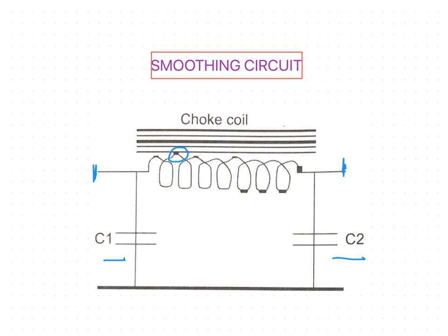When the EMF of the rectified current rises, current flows in the external circuit, and at the same time the condensers are charged. When the EMF falls, the intensity of the current in the output circuit falls, but the condensers discharge round this circuit, and it does not affect the flow of current, so the intensity does not fall to zero.